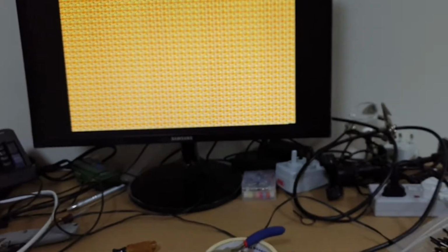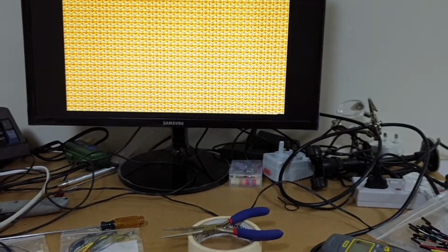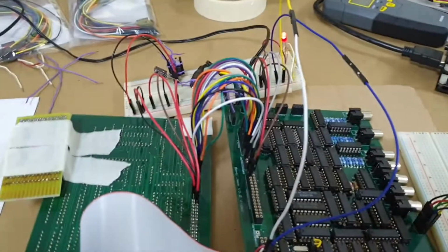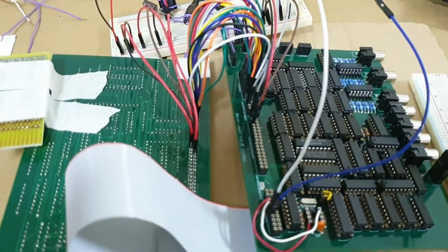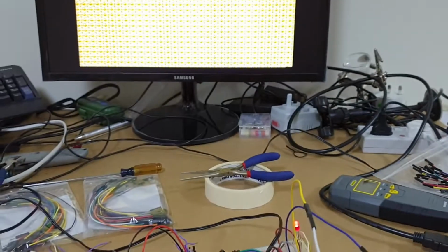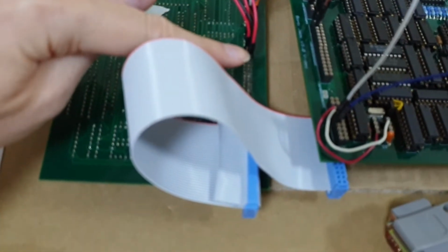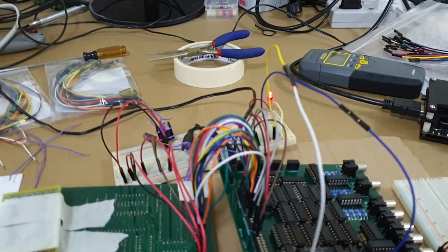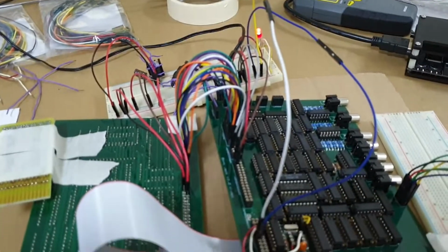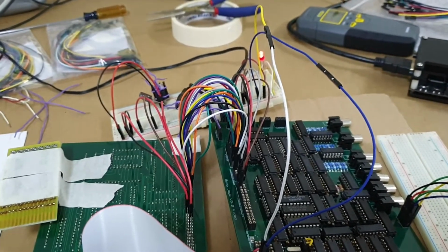So I'm not overly surprised that I'm seeing these kind of analog electrical effects coming into play as the board was like this. Now, when I had the pins here going into the sockets here, into the headers directly, I didn't really notice these kind of effects. I'm not surprised, because the pins underneath the video board go into the sockets of the character generation board. Yes, the character generation board is on the bottom. That was a rock solid, very solid connection. It actually took a lot of effort to disconnect them again.